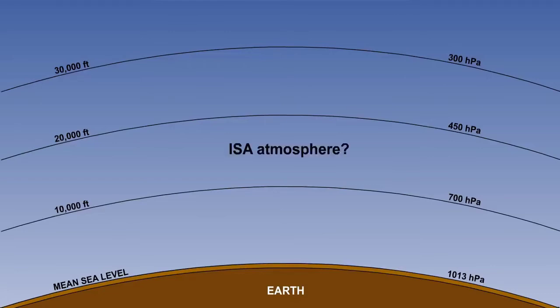But remember, these pressures will only be found at these levels on an ISA day. However, it would be very unusual to have a day which is exactly the same as the ISA atmosphere when you fly. This standard atmosphere is an average for all the regions in the world, from tropical to polar, and all the seasons of the year, hot or cold. Therefore, the altimeter is extremely unlikely to read your true altitude. This may be for one or two reasons.